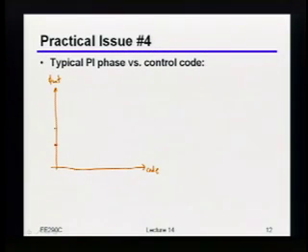And let's just assume that, for the sake of simplicity, I have 4 phases that I feed to the input, that I mux between. So I would have 0 degrees down here, 90 degrees there, 180 degrees there, 270 degrees here, and then, of course, eventually I'll have 360 degrees. Okay?